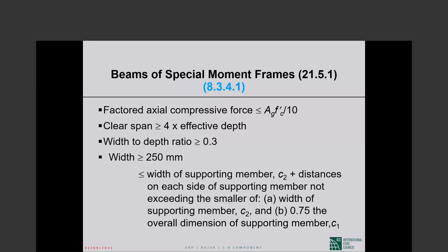Okay, the second question is much easier. When I said repeatedly flat plate column frames are not allowed in seismic design category D buildings, I always say it as part of the seismic force resisting system. They cannot be part of the seismic force resisting system. That does not mean they cannot be used in design category D buildings. They are used all the time.